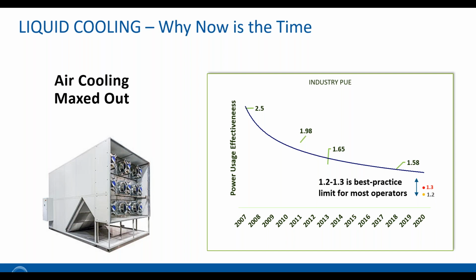So temperatures beyond 27 degrees Celsius. Generally speaking, although physically and technically it should be possible, simply because it also opens up lower temperature bands to buy back lost life cycle time, the bottom line is we don't really see that happening, because it suddenly becomes not really acceptable for commercial or business case reasons, and that really puts a hard limit, if you like, on what air cooling can achieve in terms of efficiencies.